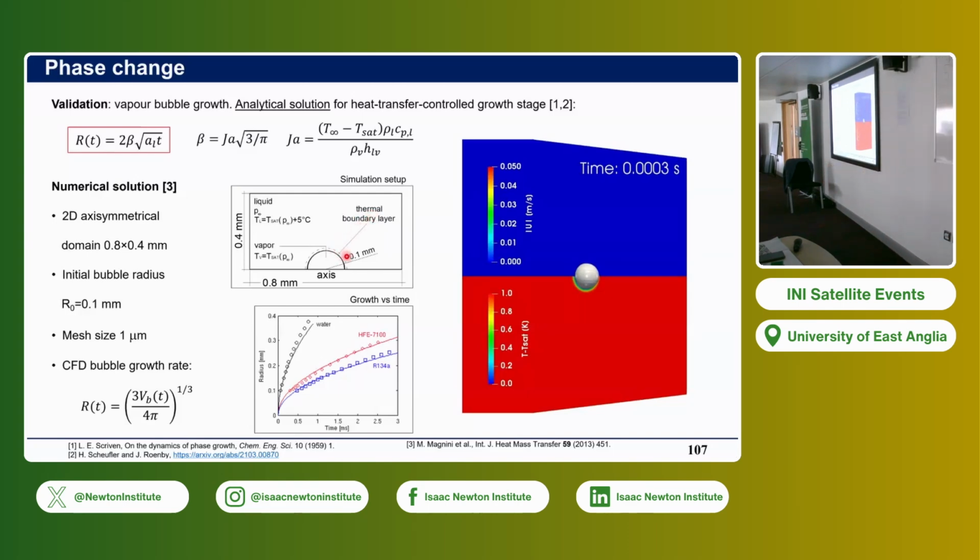So in the simulation, we need to start with this boundary layer here. Otherwise, we don't capture well the following dynamics of the bubble. Because if we start brutally this way, obviously the interface at time step 0 will find an enormous evaporation rate because of this jump. So you would get a growth of the bubble which during the initial time steps is not correct. So in the simulation, we have this thin thermal boundary layer imposed by the solver.